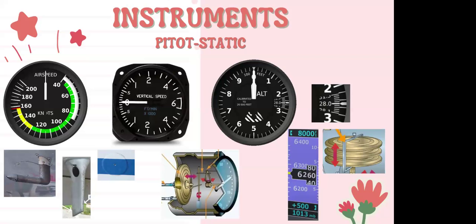They get thinner. That's exactly right. So because of that, if we didn't also measure against the static air, which we'll get to in a minute, we wouldn't have an accurate reading. So that's why we use both the pitot and the static port.